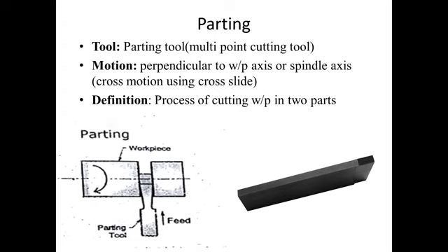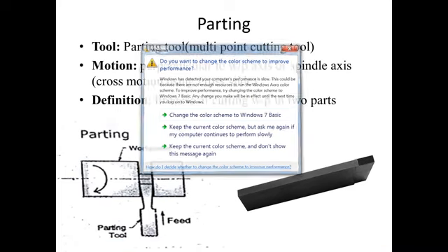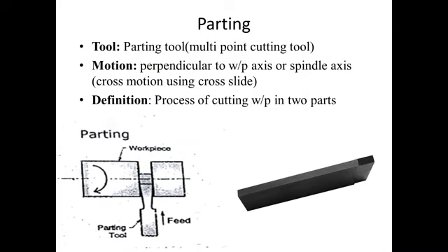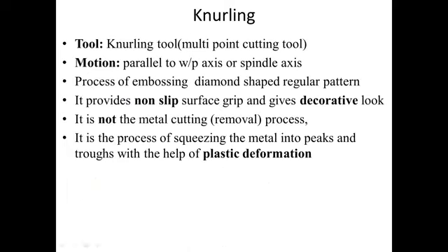So we are parting the workpiece. Cutting the workpiece in two parts, that we can say is parting, and that's the difference between parting and grooving. Grooving is creating a small groove inside a cylindrical workpiece.